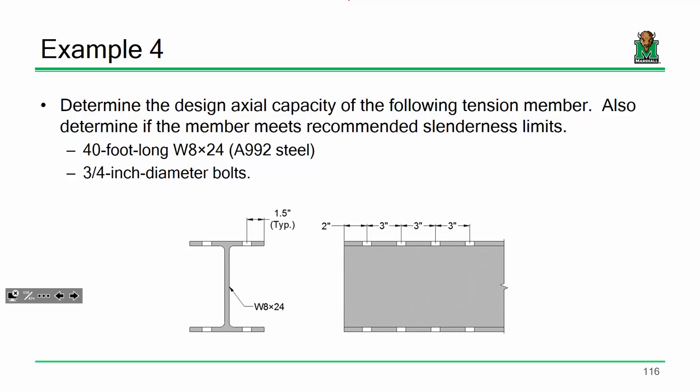Because let's be clear. Let's talk about what goes into those numbers, okay? Remember, we take the dead load and we bump it up 20%. We take the live load and we bump it up 60%. We take the fracture capacity and we bump it down. We reduce it to 75% of its original value. So be clear, all those factors of safety are already built in. You know what I mean?